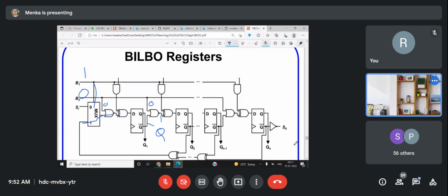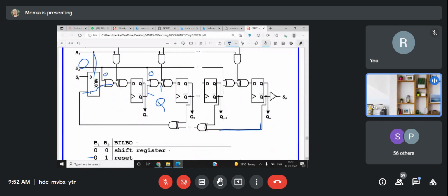This was qn, and the opposite of all these bits is taken, and this is XORed, and then it goes to the input of this. And from here, whatever you have, just the opposite of that you will have over here. This was 1, so this is 1. Correct? This was 0, so whatever q bar is there, this is appearing as q. So what will come here? 1 XOR with q, you will get q bar. Yes or no?